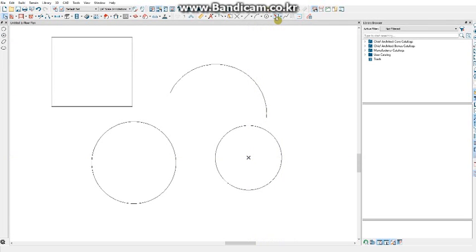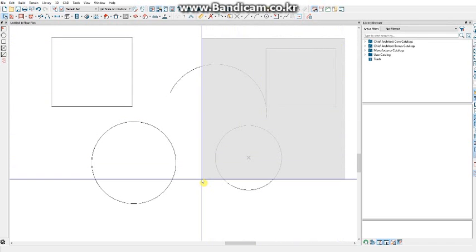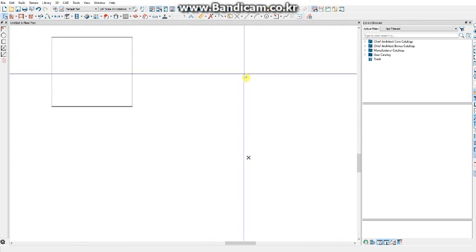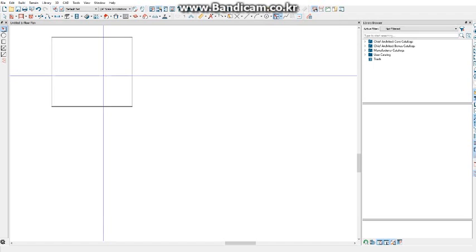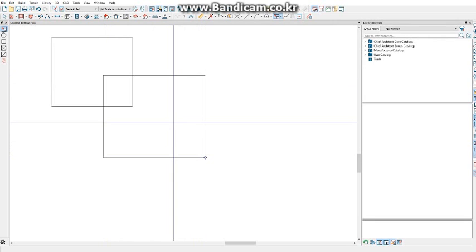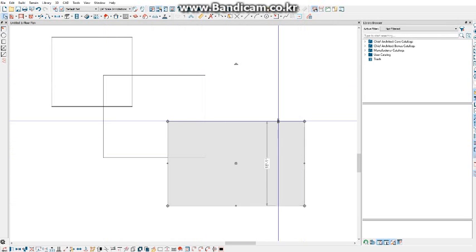You also have the Rectangle Polyline parent tool. Here you can draw a rectangle polyline by clicking and dragging to form the opposite corners of a rectangular polyline. I'll go ahead and delete some of these objects, and then I'll draw 2 more rectangle polylines. Now we'll take a look at editing CAD objects.